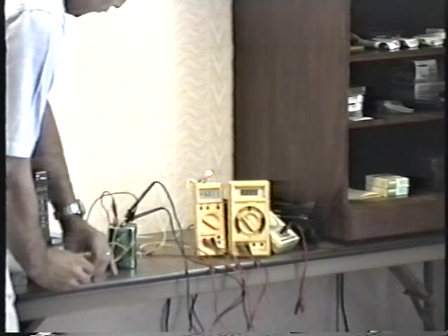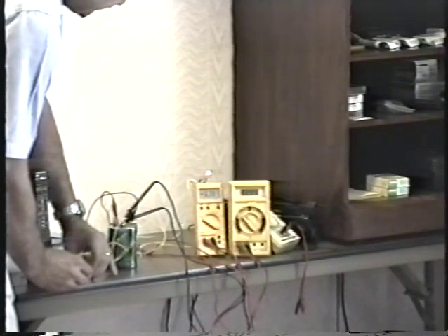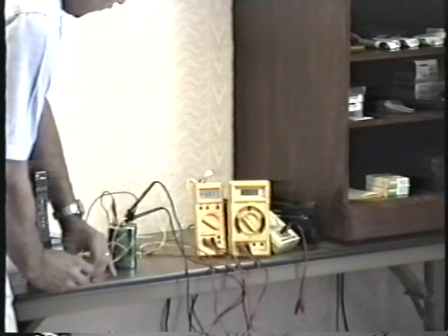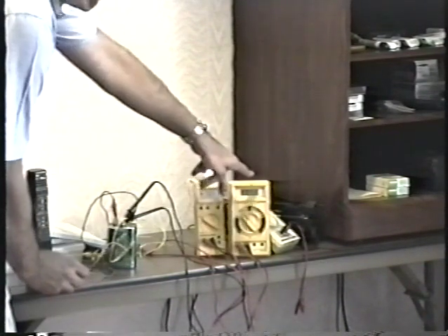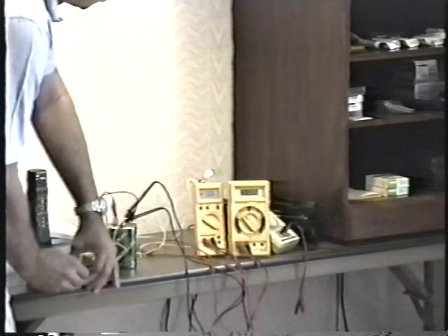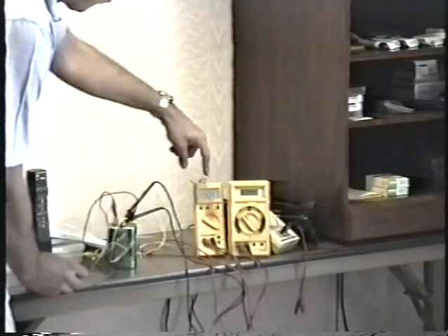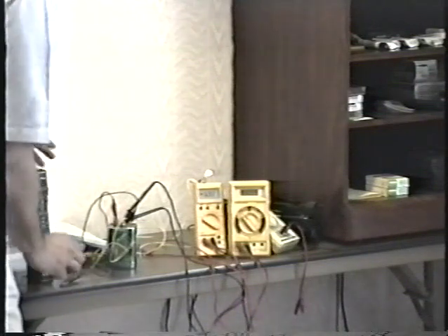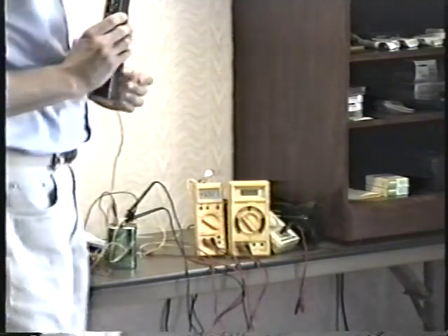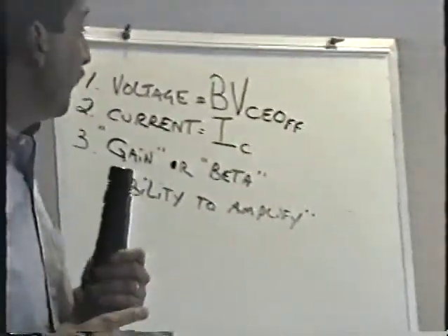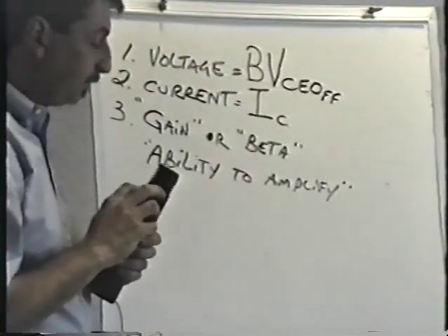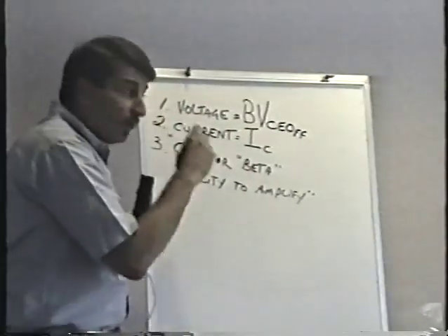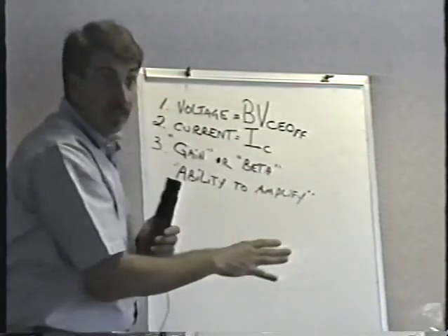Like we went, at 0.66, the thing was dim, but at 0.7, just 40 hundredths of a volt later, it was up full bright, and we had the collector drop to 0 volts. It only takes a fraction of a volt change on the base to produce a much larger change between the collector and the emitter. Remember when we did the experiment, just 0.04 of a volt change on the base produced a 3 volt change on the collector, didn't it?